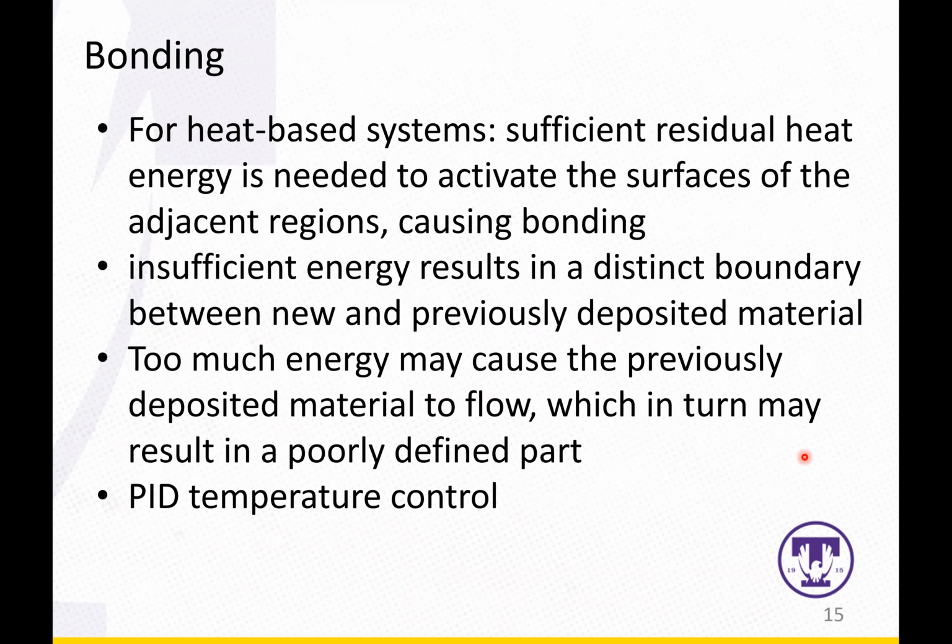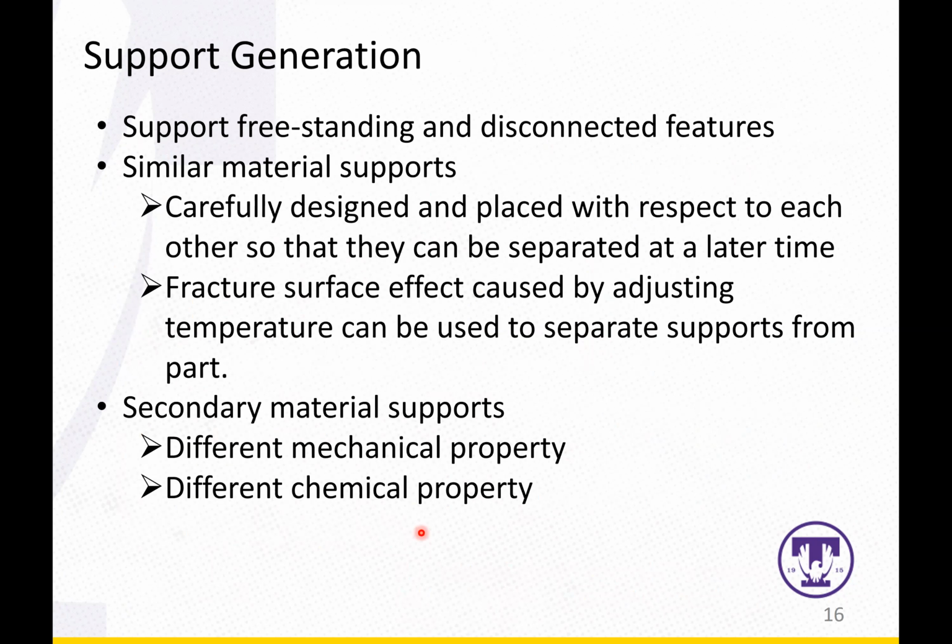So you have to control this energy very well, to make sure the residual thermal energy is not too much and not too little. So that is why temperature control or thermal control is very important for fused deposition modeling.